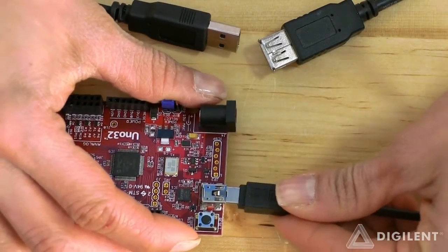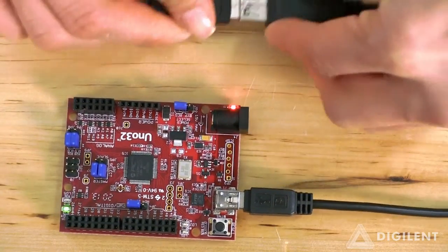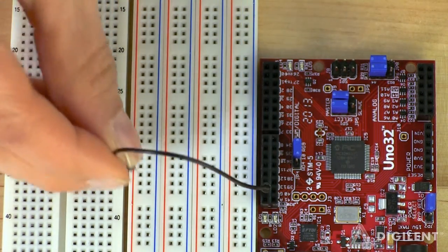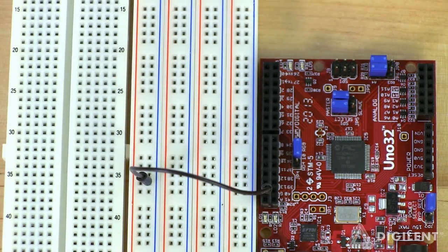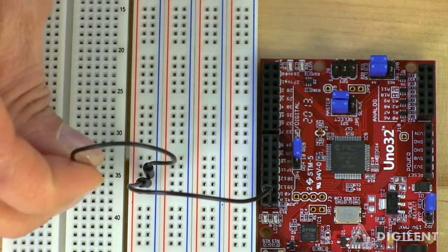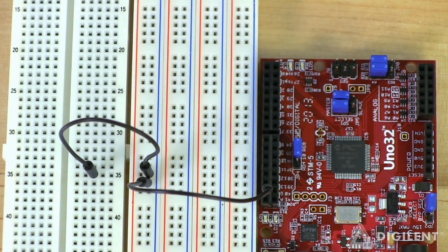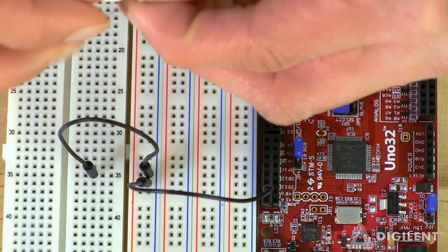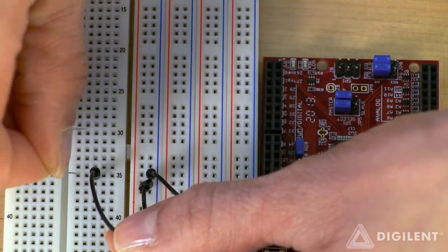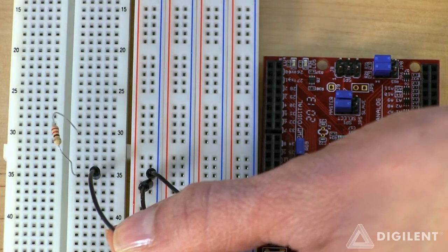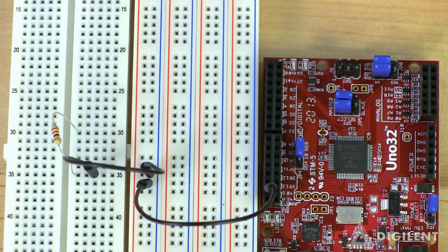First, connect the Chipkit board to your computer. Next, connect the ground pin to a rail and then to the resistor. Setting one rail to ground is a good habit to develop because it reduces the clutter of circuits you implement. Next, place your 220 ohm resistor on the breadboard with one end connected to ground. This will be your current limiting component, and it should be connected in series with the LED.